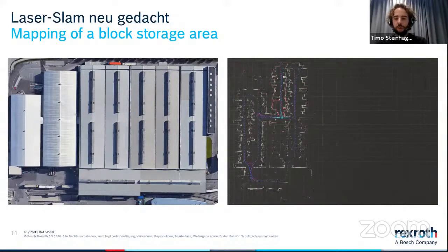Yeah, so this goes on for a while. And what you can see here, we just have the laser sensors, so there's no further integration needed. In the case of the fork truck, we don't have wheel odometry, which we could integrate if you use a particular short-range laser scanner, or if you have some free spaces that you want to cross. We can integrate wheel odometry, but the laser scanner is our main sensor, and it's automized in a way that the map building process is done on the fly, and there is nothing else you need to do.